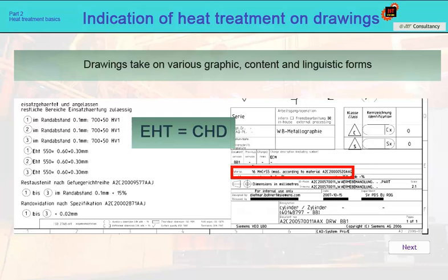It is therefore necessary to maintain some knowledge of the historical context and then transfer this knowledge to the current standardized state. When checking the drawing values, it is also necessary to pay attention to the fact that the drawing specifies the maximum value of residual austenite in the carburized layer up to 15%, as well as the value of the internal oxide layer to a depth of 20 microns. According to the new designation, this value should be marked with the abbreviation IOD, in English Internal Oxidation Depth.